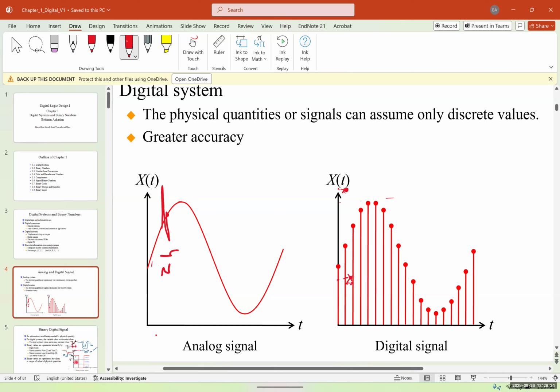It's much easier in a digital system than an analog system. So for this particular one on the left, if you want to filter out this part, you actually need to build hardware for it. You need to build a circuit, which usually could be a high pass filter, or a band pass or a low pass filter or something like that.